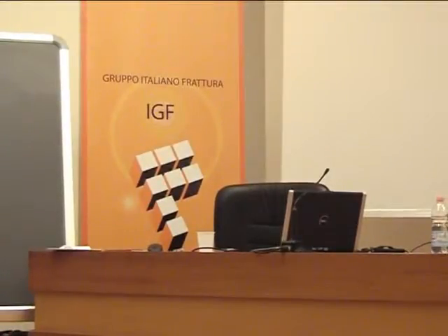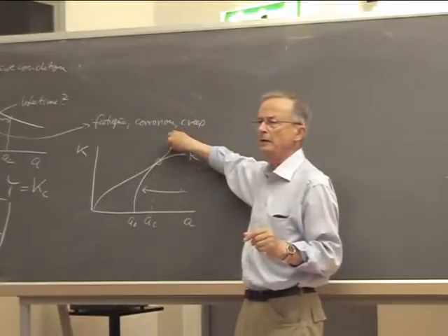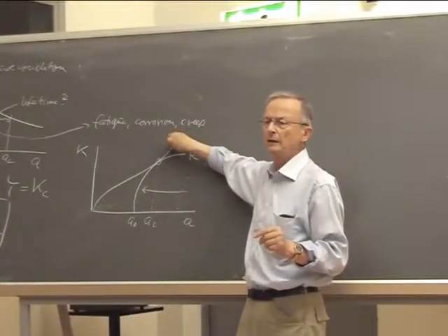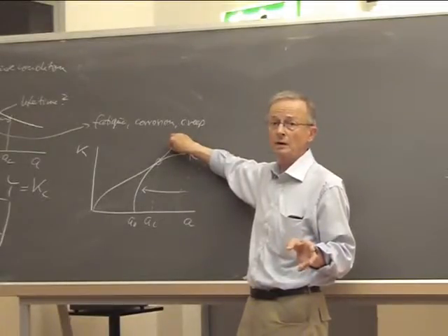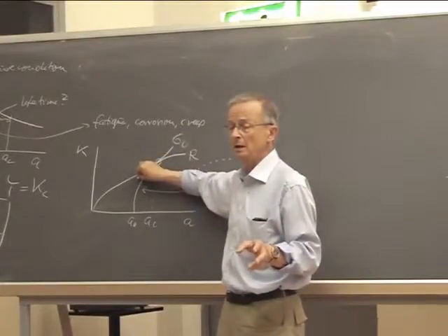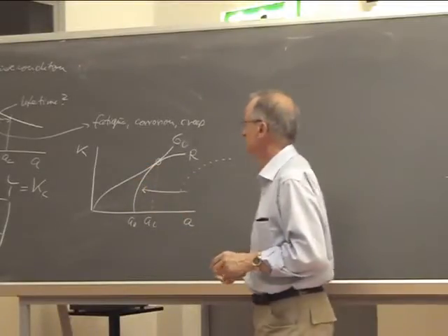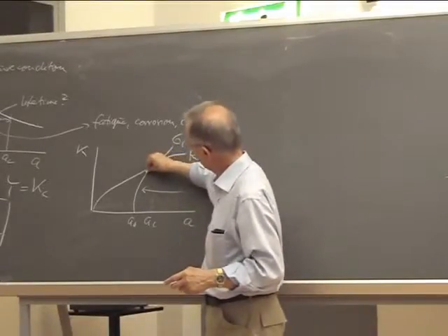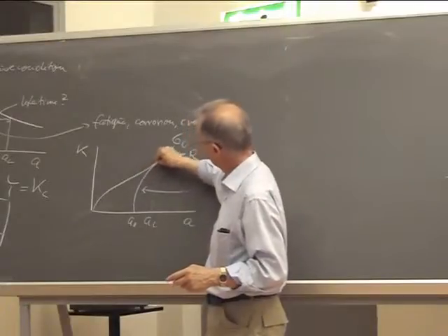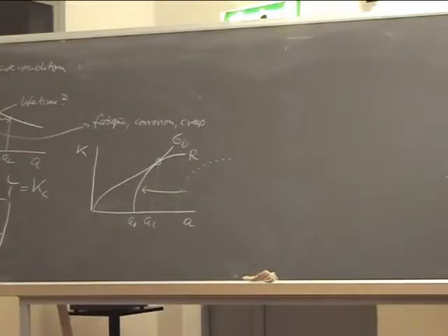We should keep in mind that the R-curve here is a material property, and the driving force curve is a property that depends on geometrical parameters for a given stress. So with another geometry, you have another driving force curve. For short cracks, the tangent condition goes down, and for longer cracks, the tangent condition goes up. It can be easily seen by the geometry of this construction.